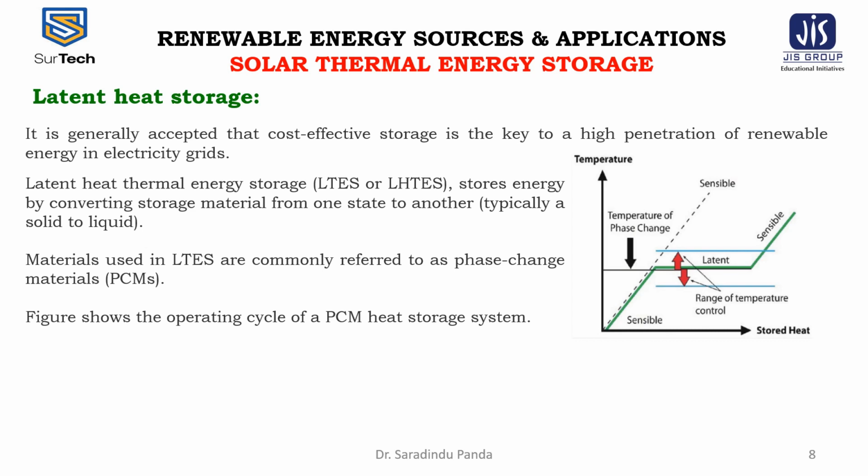Medium solar storage temperature is generally higher than 100 degrees centigrade, but under 500 degrees centigrade. Usually it is around 300 degrees centigrade. Suitable materials for medium temperature storage are high pressure hot water, organic fluids, and eutectic salt.